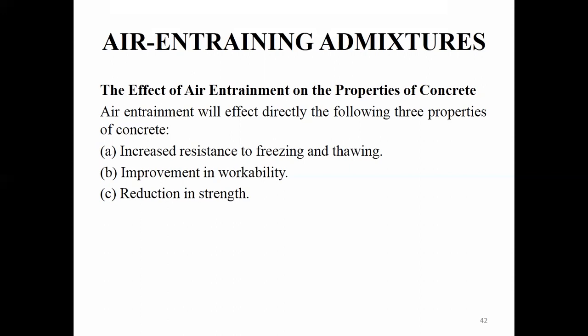Okay, and also due to some improvement in the workability because of this air entrainment, there are some things we should consider here. One is when you are proportioning the concrete mixes. Proportioning means deciding how much cement you need, how much fine aggregate, coarse aggregate and so on, right? There you will be discussing workability, and other aspects such as strength, durability, volume stability and so on.